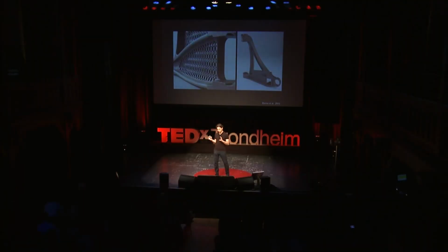So we actually end up with the program of the object directly, which means that you can incorporate simulation as part of the modeling process, and what we call fitness. Fitness is where you have a criteria for what the object should meet. For instance, in this case, this is a control arm for a car, and what we wanted to do was see that it was 10% lighter while maintaining its strength.